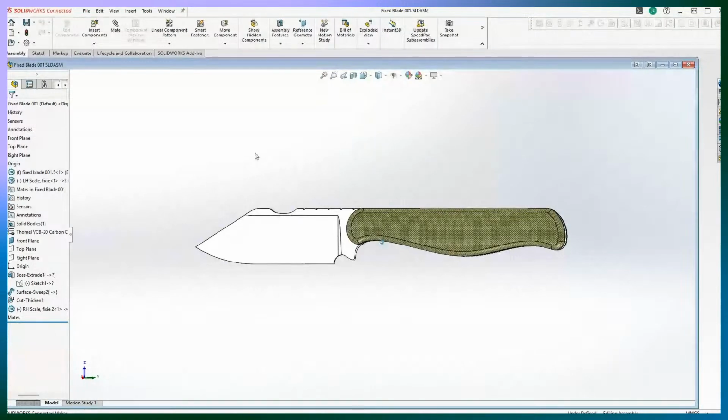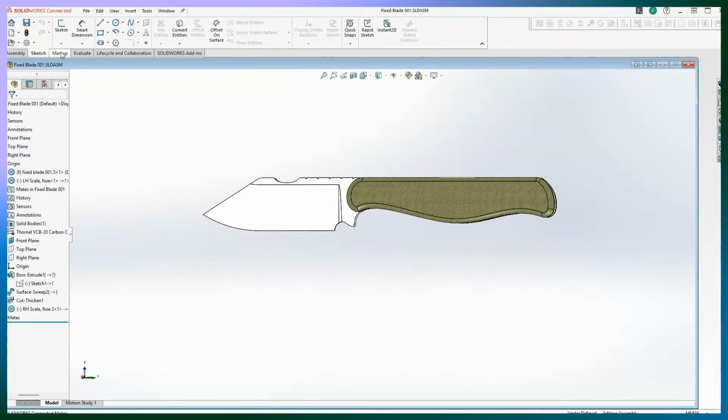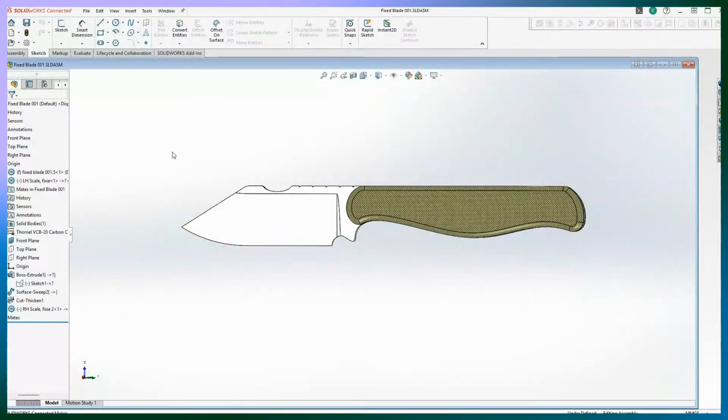And what I did was, you can import a sketch image into here. So I imported a photocopy of an actual hand sketch, and then he had dimensioned it, which is really nice. So you can shrink the image and expand it until the dimension on the drawing matches the dimension in 3D or 2D. Well, on a 2D plane, but in 3D.